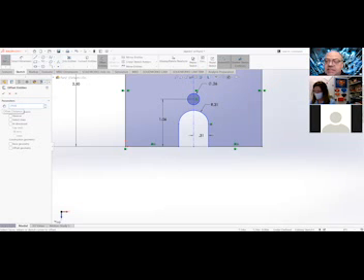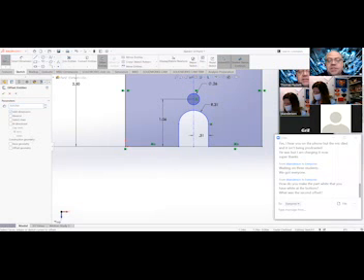So it's 5/16. Remember, if we double the denominator, we cut the fraction in half. I could put in 5/16. I could even put in 5/8 and then divide that by 2, which is a crazy math equation, but SOLIDWORKS can do that. You can divide a fraction in SOLIDWORKS.